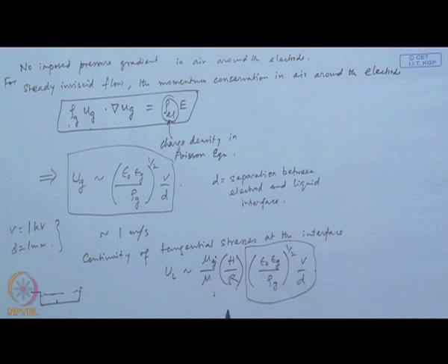So, you can work with this UL, and one can see that this UL would be coming to about 1 centimeter, I mean, it depends on what kind of geometric ratio you have here. It can be related to the gas side velocity, and one has shown that this has substantial liquid side velocity which can give rise to circulation, that is meaningful.